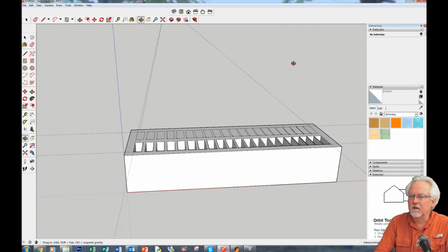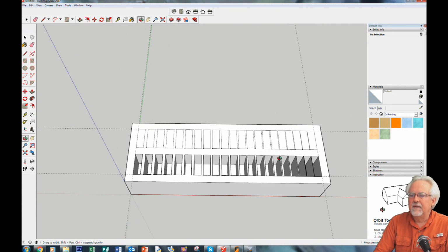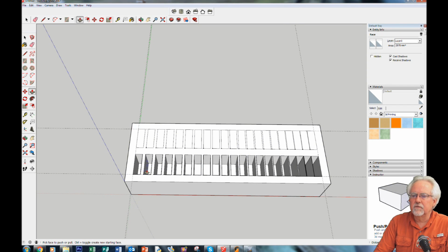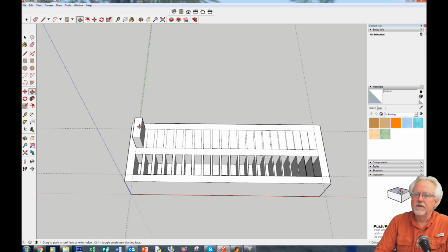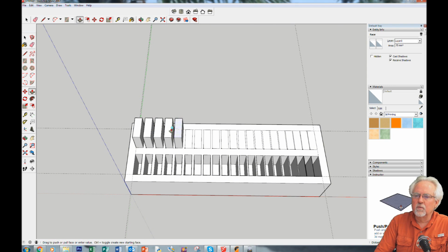Yeah, so we've got all of those as holes, and the spacing between these slots goes from 2 millimeters all the way down to 0.1 millimeter. Right, these we want to make columns, and so I'm going to select this, and I'm going to come up, how far? 15, enter. So that one's 15. Now we should just be able to kind of go to town, I think. Okay, reference to that. So here we're making columns with different spacings between them.